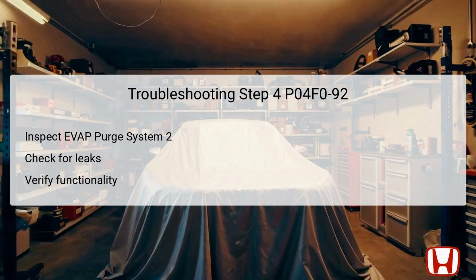Next, the focus should shift to EVAP Purge System 2. This requires disconnecting critical components for inspection to check for leaks or restrictions. Following the disconnection, connect a vacuum pump to evaluate the integrity of the system. Apply pressure to ensure that it holds without signs of leakage. If pressure drops, this indicates a potential fault.